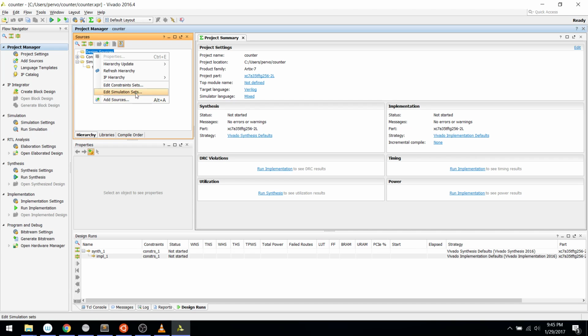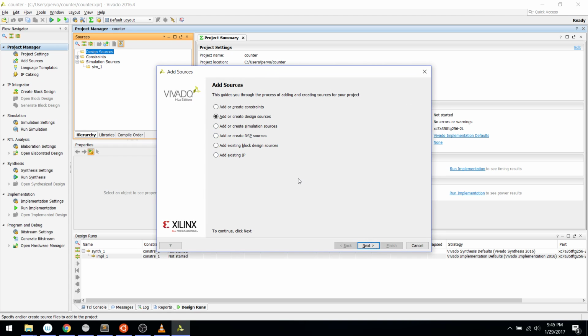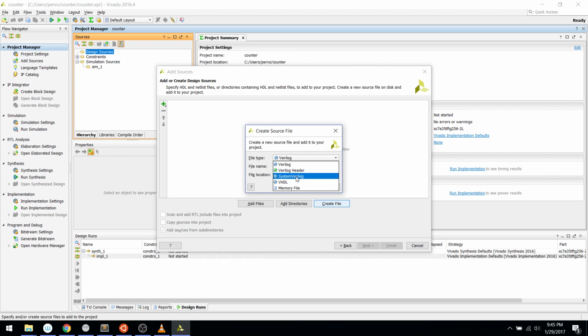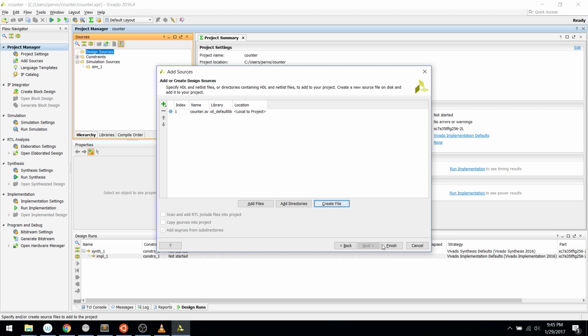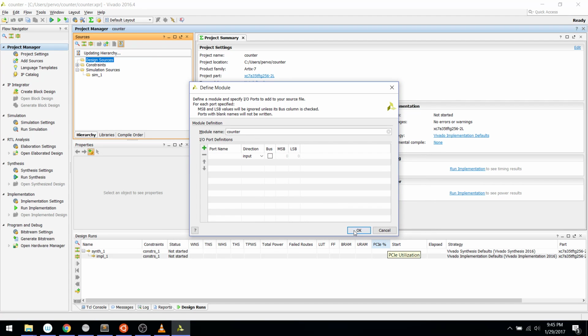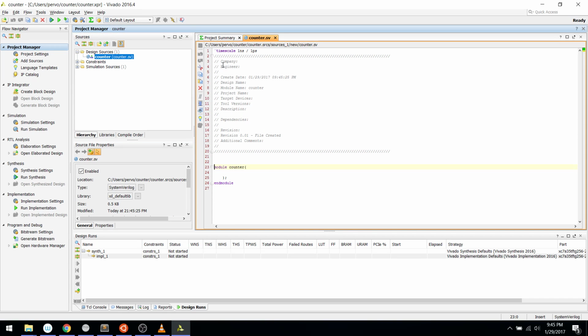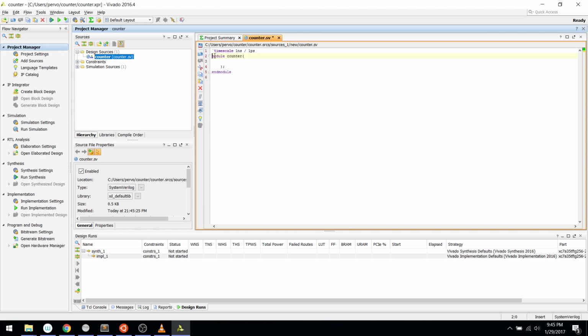So first thing we have to do is add a source file for design, for RTL code. A lot of this stuff is pretty tedious, a lot of dialogues. So let's call that counter.sv, SystemVerilog versus Verilog. Just take these defaults. That's fine. All right. So it generates a stupid file with the timescale definition. It's probably fine, and an empty module.